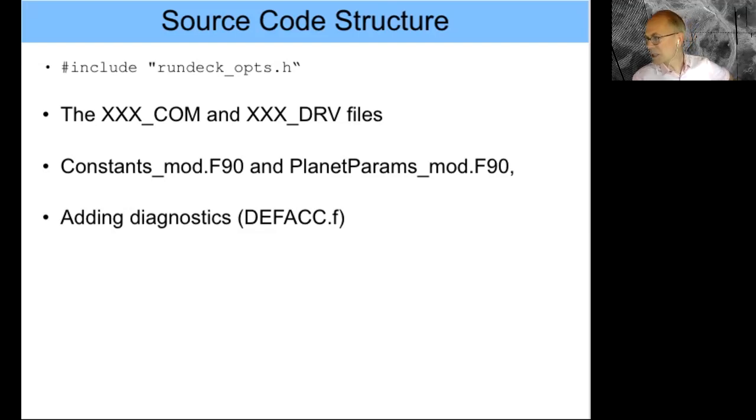That goes back to something that Tony mentioned, this NDisk parameter, where these fort files are written out every X number of time steps. Let's say you're running on a small supercomputer and you're running 10 jobs. You might want to make this NDisk number a bit larger, 2 or 3 times the default, so it's not spending huge amounts of time writing out these fort files more than it needs to. We recently had this problem on our own supercomputer at Goddard, where we were recommended to at least double that value because the I/O on our main file system was being overwhelmed.